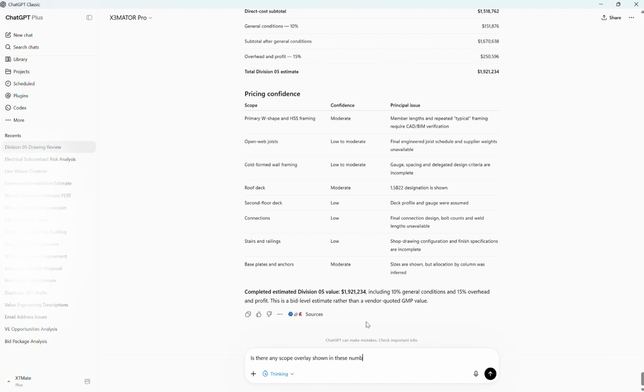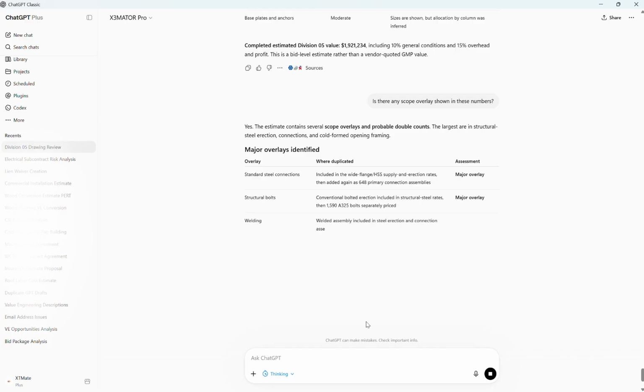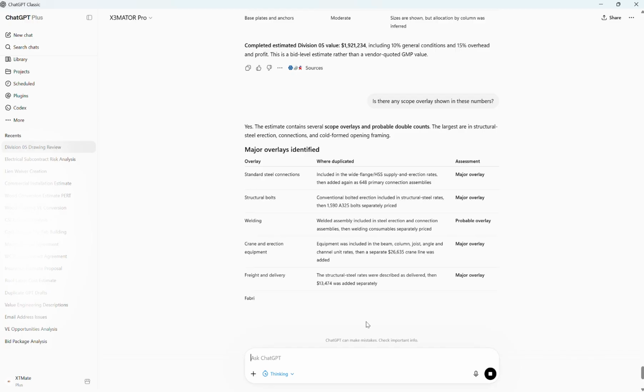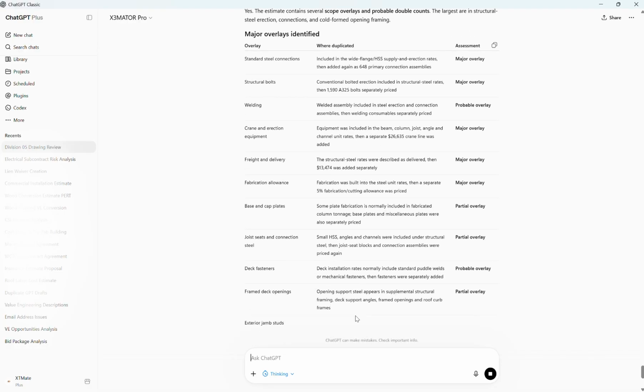Now look at the level of detail. Roughly 67 tons of structural steel, including the joist and the connection allowance. Over 1,800 linear feet of wide flange beams and girders in the W8 through W16 series. 40 HSS columns at just under 500 linear feet.